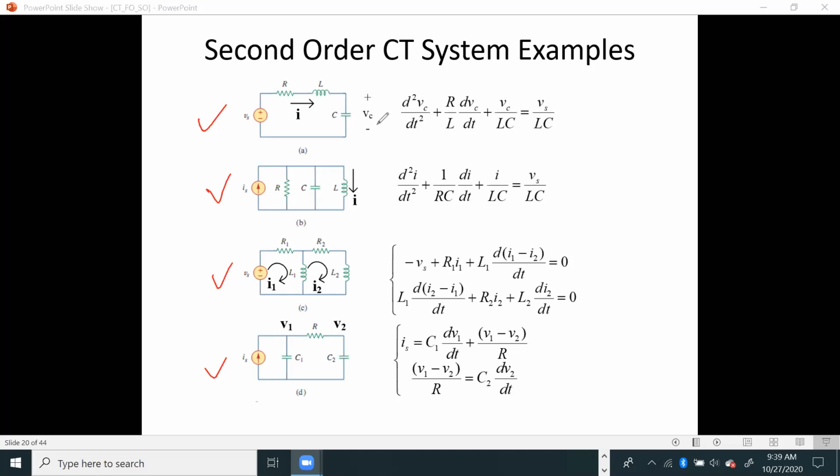But the order of your system will be different. The reason is that these inductors L1 and L2 are not connected in the same electrical locations. Electrical locations means they do not have anything in common in terms of current or voltage. Are those things common to L1 and L2? No, sir. Because they are carrying different current and the voltage across them is also different.